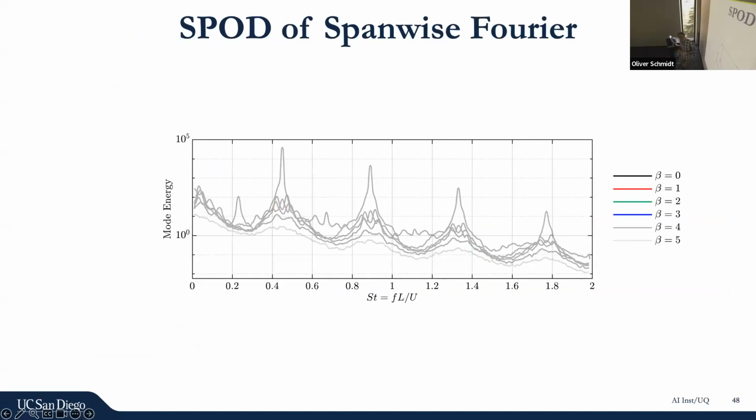This is just a power spectrum. This is an SPOD power spectrum. So these are SPOD modes. This DNS was computed with periodic boundary conditions in Z, so we can just separate out, with no loss of generality. We can just take the Fourier transform in the spanwise direction and look at the different components.